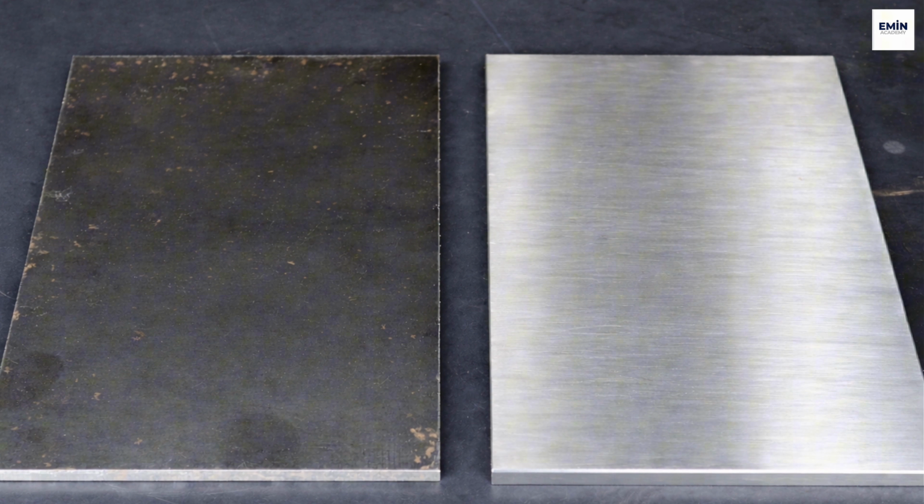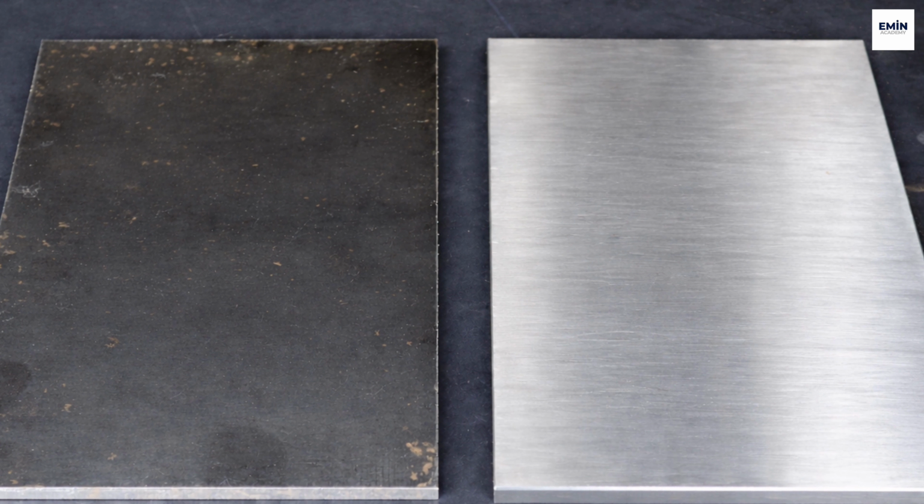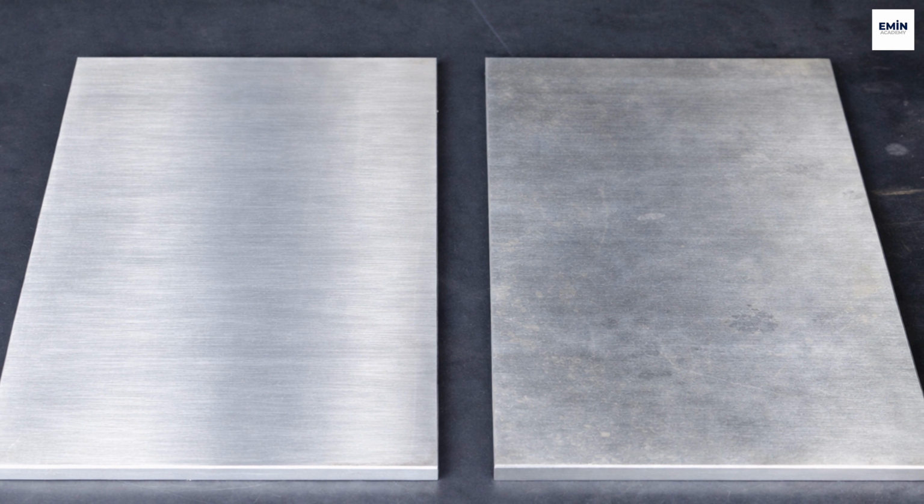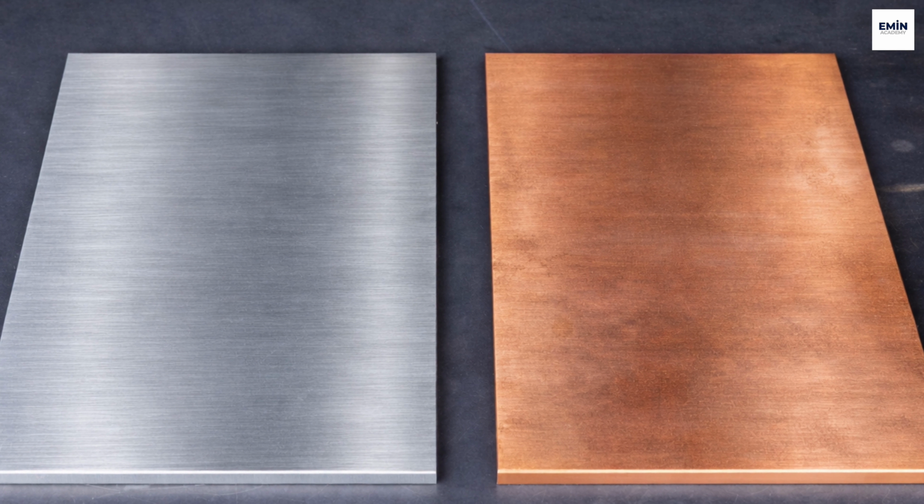The rule is actually very clear. Steel and stainless steel, DC electrode negative. Aluminum and magnesium, alternating current. Titanium and copper, DC electrode negative. What happens if we try to weld aluminum with direct current? The oxide layer doesn't break, the bead becomes dull and dirty. Penetration weakens and weld strength decreases. So the problem is not in the settings, but in the polarity.